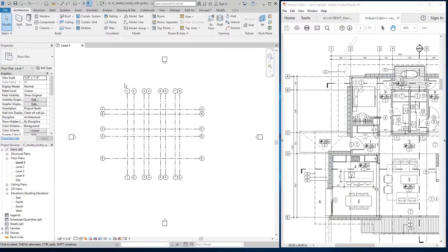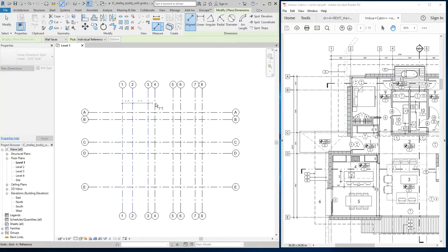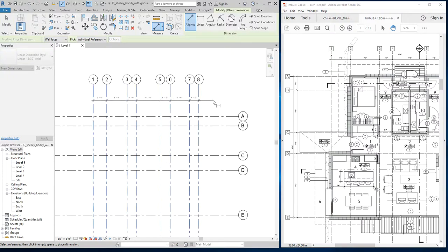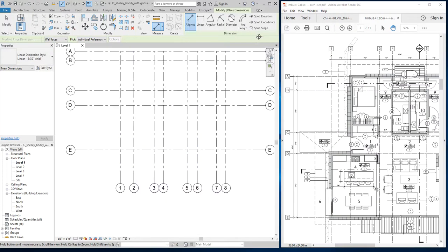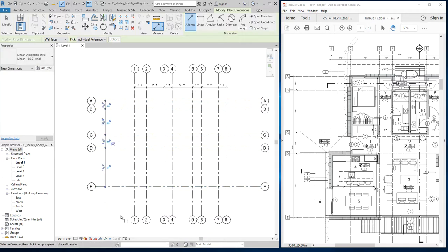And like I said, I'm going to draw a quick dimension. We learned that was DI, dimension. We only know how to do one type of dimension, click, click, but I'm just going to quickly create those, click, click, and it creates the whole string until I click in nowhere land, click, done. So nice and easy and scaled, and we don't have to set anything up if we don't want to. Click, click, click, click, click, click, and you just can't even handle it, can you?